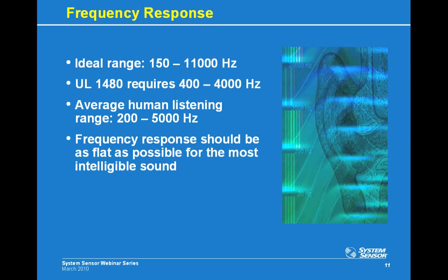And when measuring frequency response, it's important for frequency to be as flat as possible in order to produce the most intelligible sound. The flatter the response over the frequency range, the better the speaker intelligibility will be.